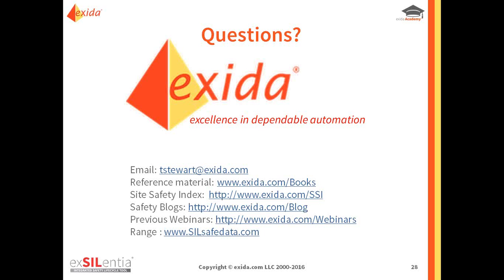So good question. Do the predictive lambdas with FMEDAs also come from manufacturer data? Well, I laugh, but if I'm speaking with Exida, absolutely not. We do not use manufacturer data. Nothing done by Exida is based on this manufacturer data. Why? Because it's so optimistic. Other certification bodies that do perform FMEDAs will include manufacturer warranty data, mainly because they don't have the database that we have. They don't have this predictive analytic kind of thing that we have.